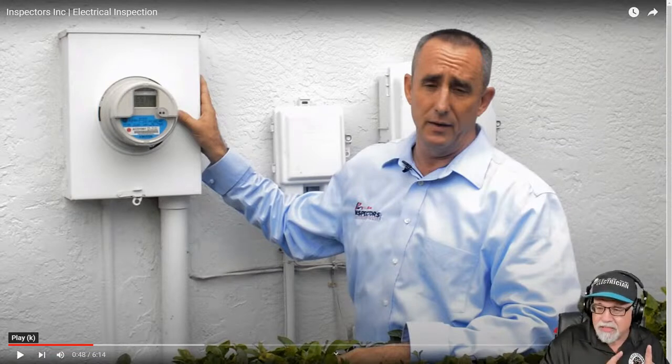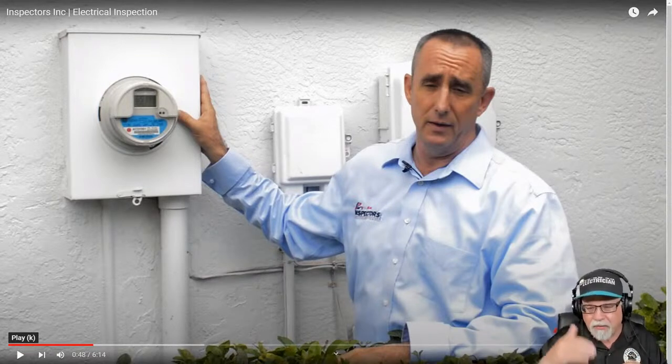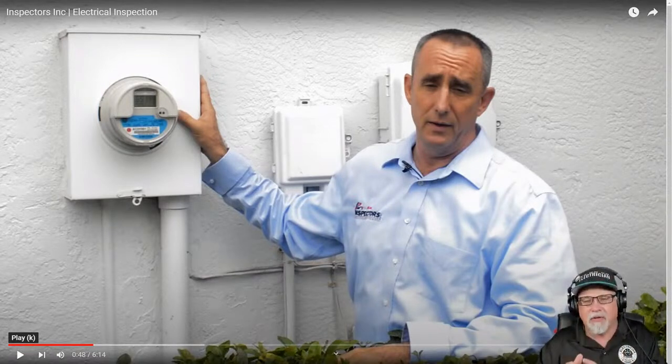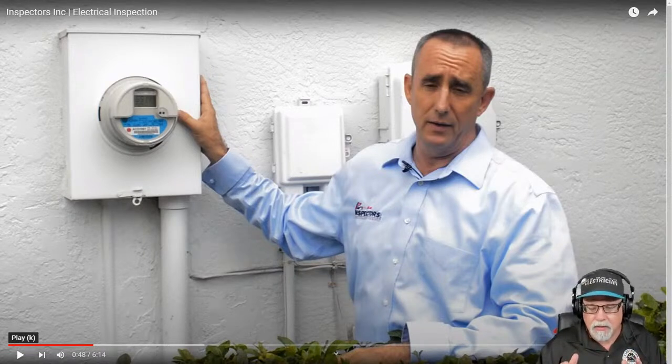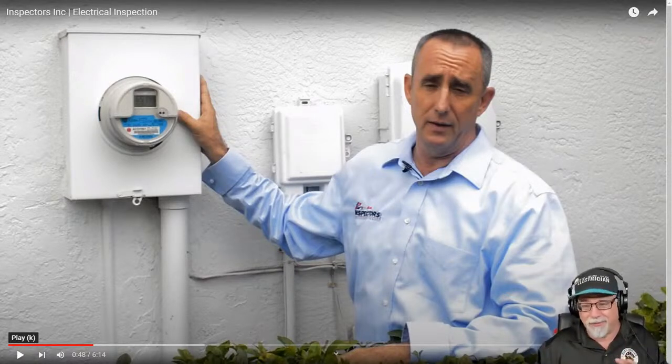He's talking about electrodes. So in 250.50, it tells you you have to have all the electrodes, you have to complete the system, and then it gives you these electrodes in 250.52, (A)(1), (A)(2), (A)(3), (A)(4), (A)(5), (A)(6), (A)(7), (A)(8), and it's different types. Ground rods are just one type of electrode, right? But again, the water pipe ground has to qualify as an electrode, not just because the piping system in the building is metal. That means you've got to bond it. But that isn't part of it being an electrode, okay? Just setting that record straight up front. So it's not an or, okay?